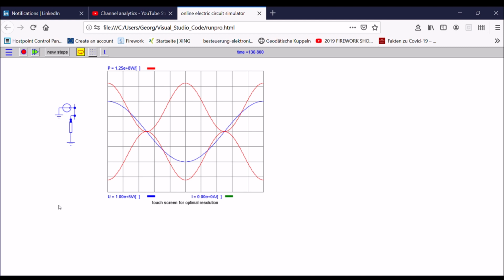This is now the most basic example of a load flow calculation. What you can see here is a power source. This is a voltage source. The source has a 200 kV peak. This is the blue curve you can see here. So it corresponds to a three-phase 245 kV system, but just one phase representation.